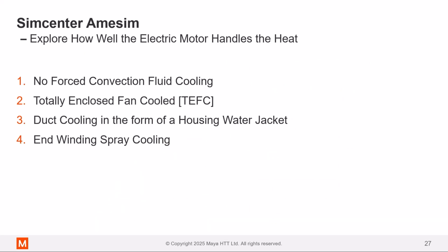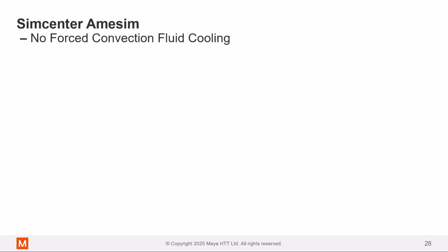At this point, we'll use the LPTN to explore what temperatures will result when we review 4 different cooling strategies. These are all shown below. Our first experiment with the LPTN will explore how the components in the electric motor respond when no forced convection fluid cooling is present.